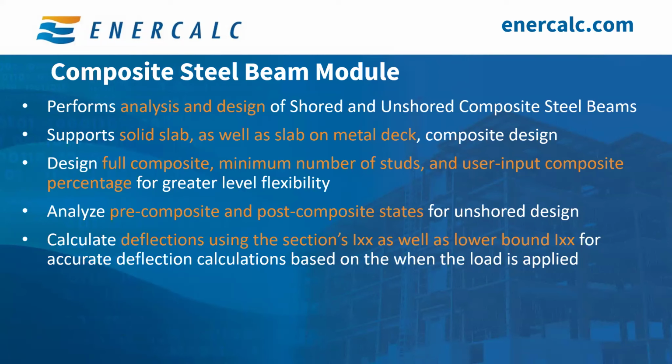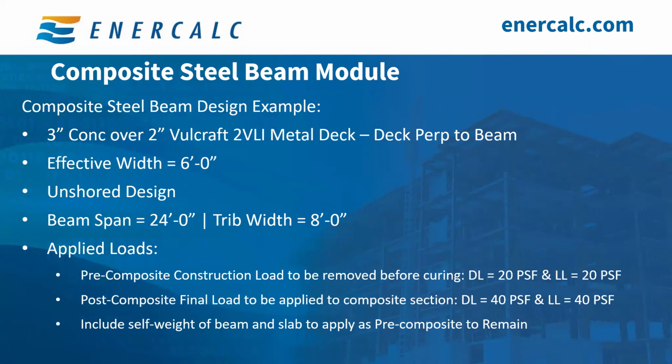You can, of course, analyze pre-composite and post-composite states for the unshored design, which is extremely critical. And then calculate deflections using the section's moment of inertia as well as the lower bound moment of inertia for accurate deflection calculations based on when the load is actually applied, whether it's a pre-composite or post-composite loading.